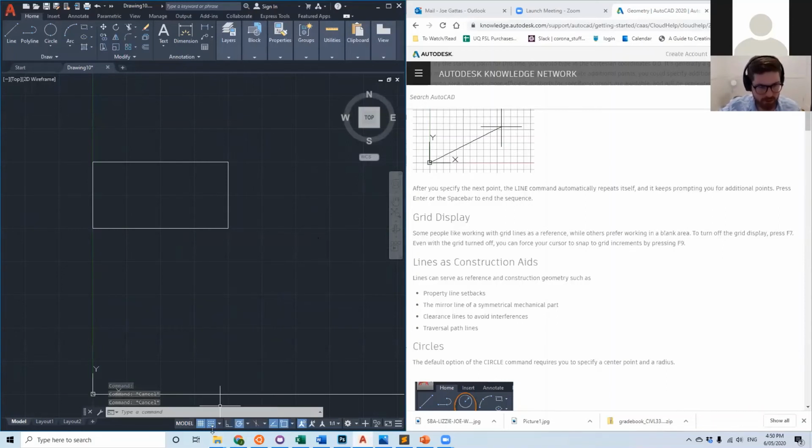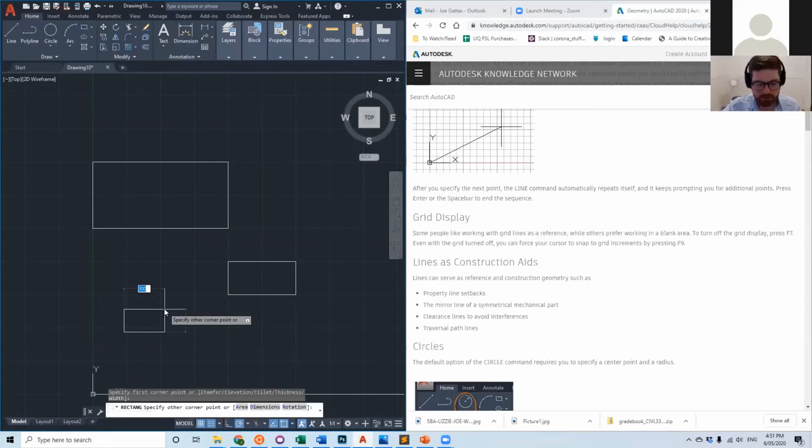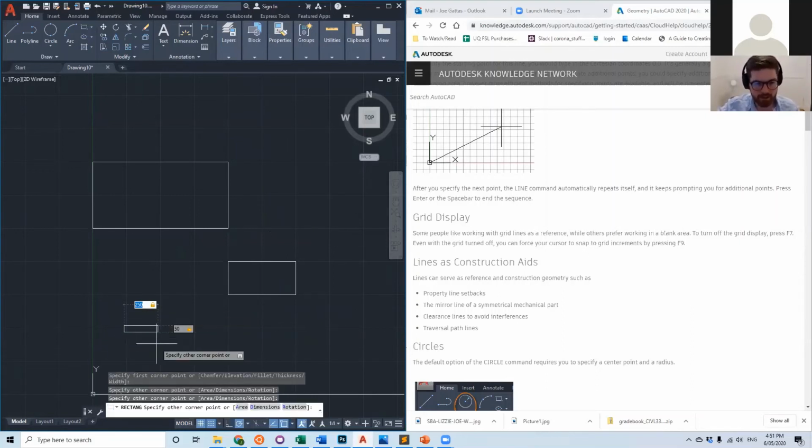So for most of your objects, you don't need decimal precision, you just need it closer to 1 millimeter or 10 millimeter. Snap mode allows you to use the grid to draw things pretty quickly. Turn it on there or hit F. That just gives you a slightly more rational starting point, like so, okay? But of course, you can just select your objects and type in what they're meant to be. 250 wide, tab, 15 meters high, tab. That's now a rectangle of that exact size.